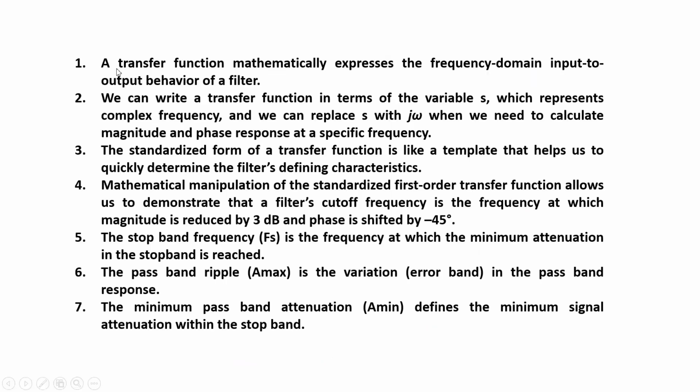Now, a filter response is expressed as a transfer function. A transfer function mathematically expresses the frequency domain input to output behavior of a filter. We can write a transfer function in terms of the variable s, which represents complex frequency, and we can replace s with j omega when we need to calculate magnitude and phase response at a specific frequency.